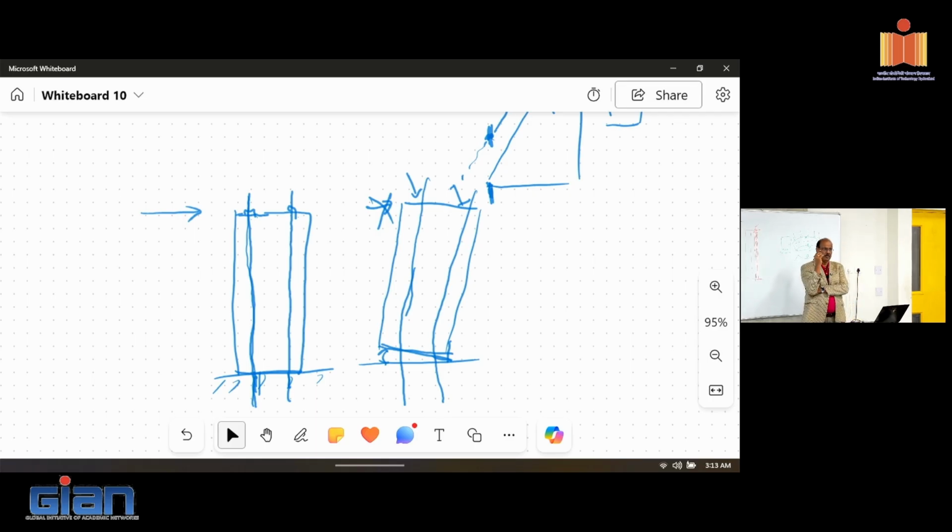Okay. What I'm saying is that if I compare the precast jointed connection detail with an equivalent cast-in-place one, the only difference is that the cast-in-place will not have a concentrated crack at the base. It will have distributed cracks, right? So let's say they both get pushed to the same, even an elastic, displacement. You will find the stiffness of this system is actually higher than cast-in-place.